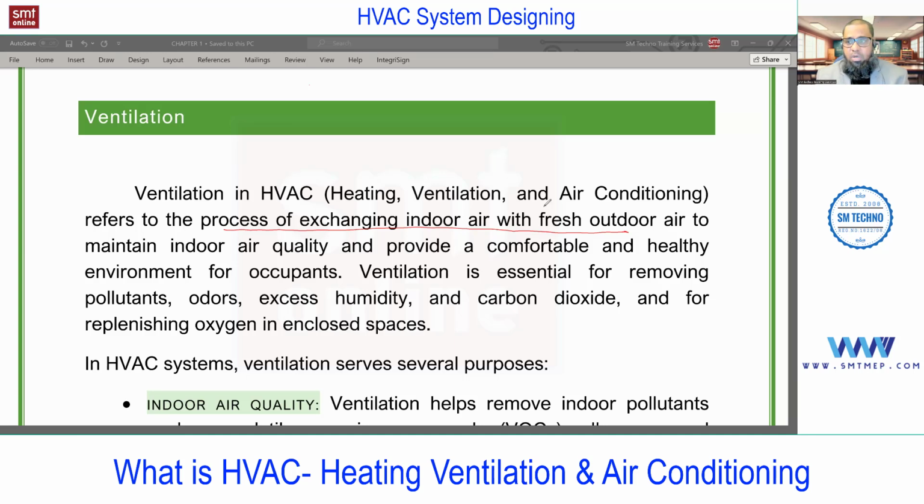Now if the room is totally packed with people, what will happen after some time? They will consume the entire available oxygen, and the CO2 level increases. If the CO2 level increases, you cannot breathe easily, and even if you are maintaining the temperature, there is no question of feeling comfortable.